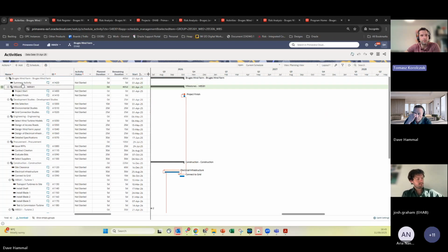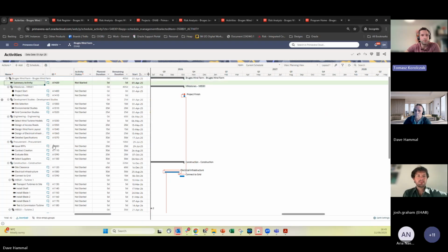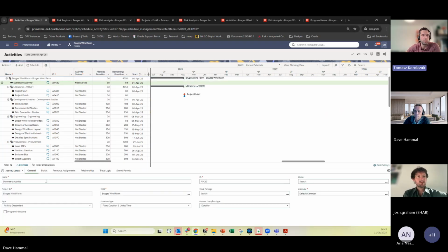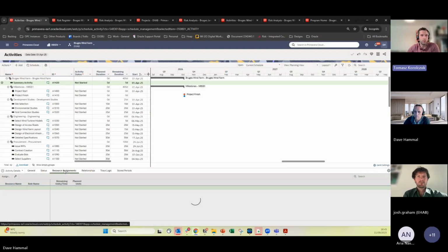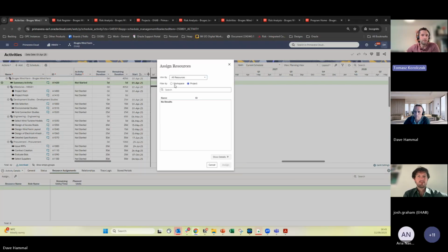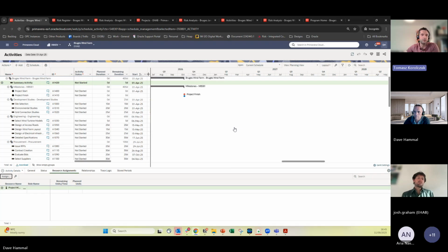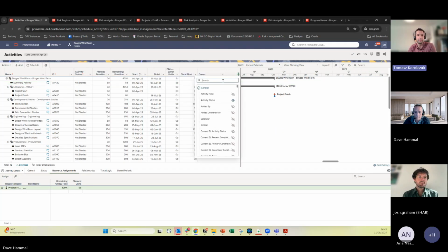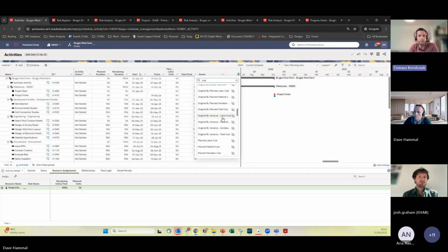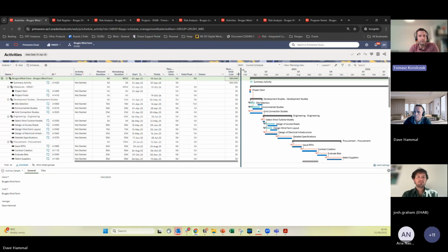If your activities are resource loaded, and we assumed a certain rate, a certain resource for 10 days, but now the duration of that activity grew to 20 days, obviously there is an extra cost associated with that extended duration coming from your resource utilization. So I know that with other risks you can account for that on OPC, but how would that look with the weather related ones?